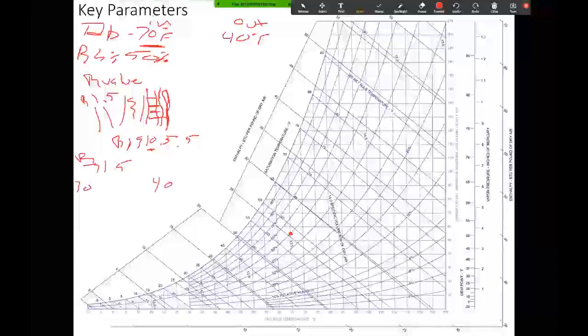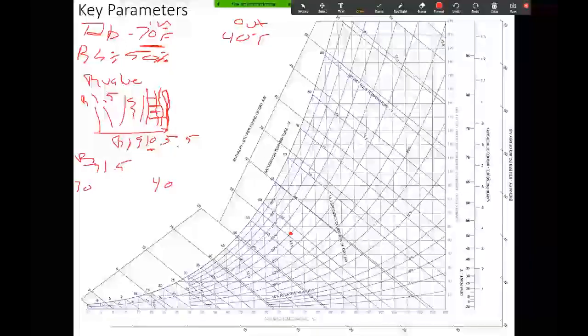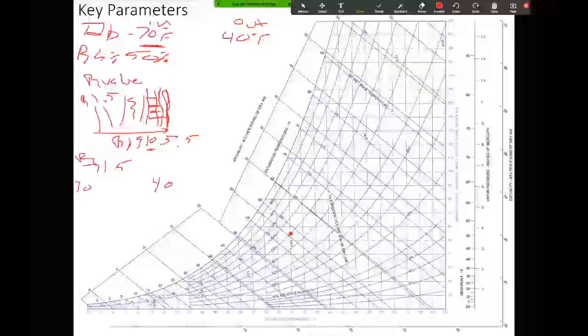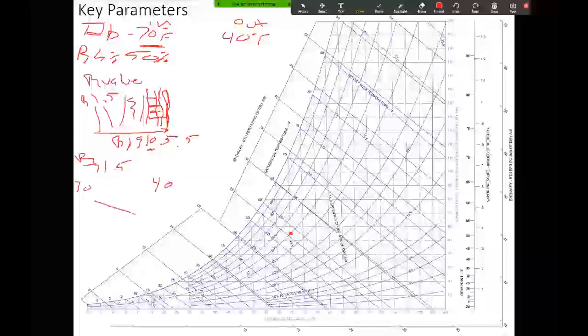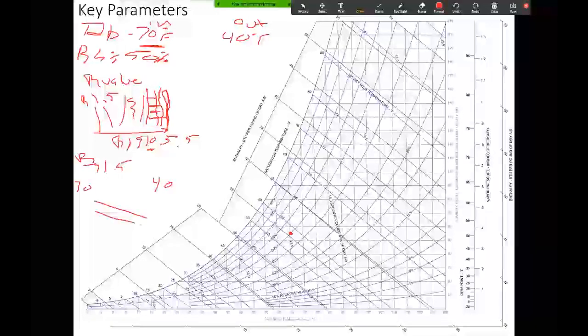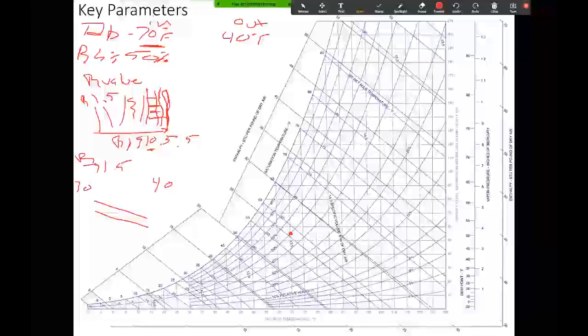As that temperature changes across that wall, it is changing in relation to the change in R value. So it changes, it's linear. So as my R value begins to decrease, the temperature follows that same pattern. Does that make sense? We'll probably look at some formulas on this stuff and how to calculate.